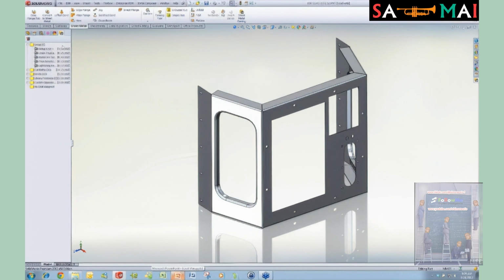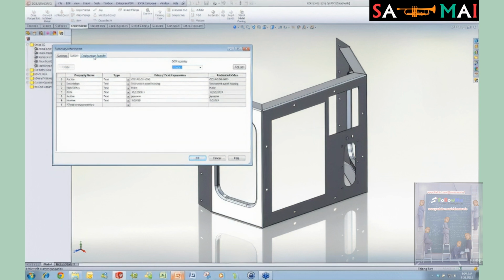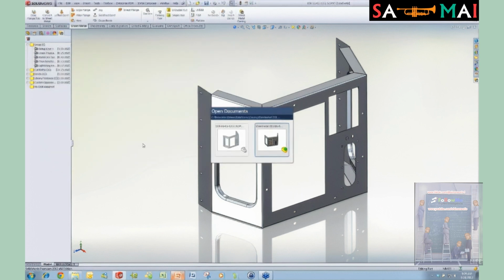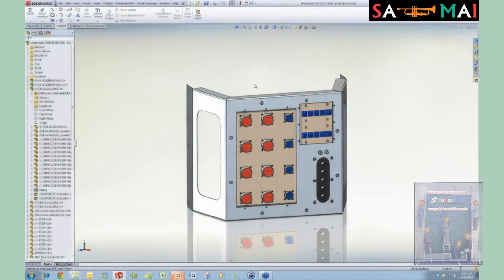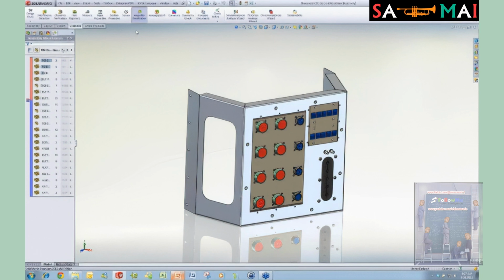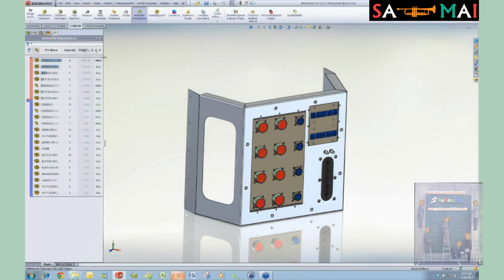One other thing that I wanted to show you was I have all this costing in this one part. Up here underneath my configuration properties, I've got the cost of this part calculated in here. So if I drop this into an assembly, since it's got it tied here to the file properties, I can push that to my EPDM system, or my PDM system, in this case Enterprise, or I can push this to a drawing. In this case I'm going here to my assembly, and I can come in here and we can show with the assembly visualization what my total cost is.